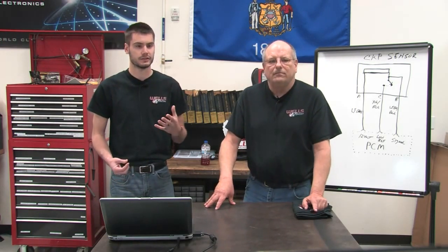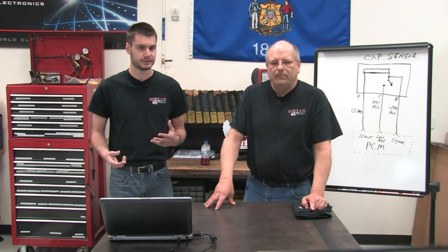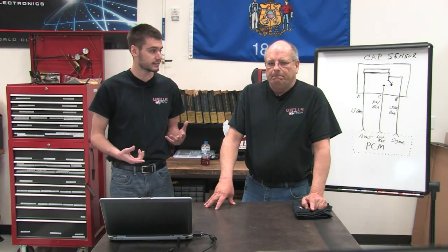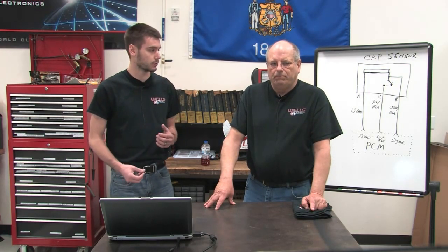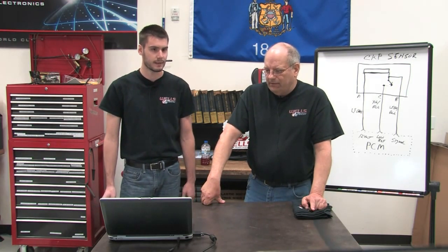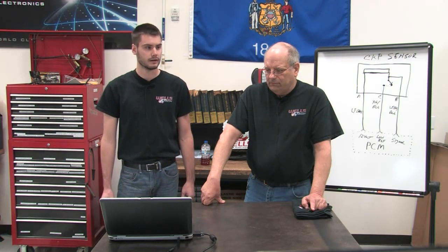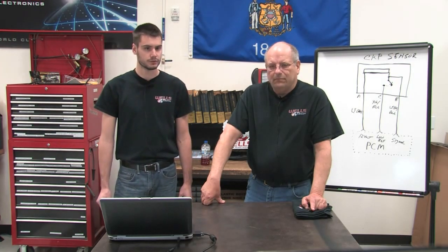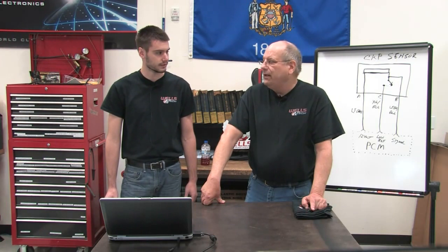You know, when we brought up the diagram here, there's a lot more aspects to this car than what we're used to seeing. This car's got 2 crank sensors, a cam sensor, and the ignition control module. Right, and that's common for the GMs of this era, the 3.8, the 3.1. It is common for these, but it's kind of an anomaly in the automotive world to be running two crank sensors. So why don't we talk about that today?